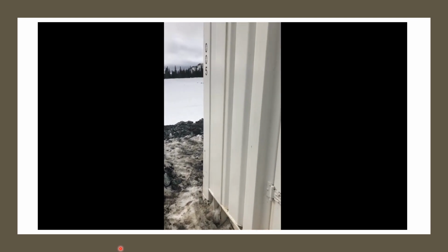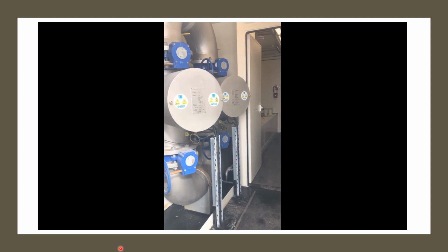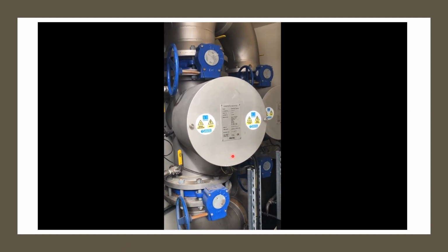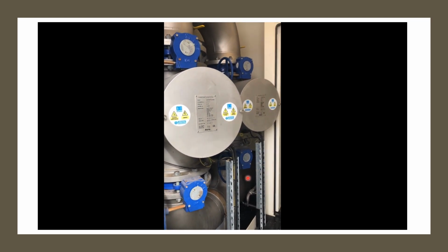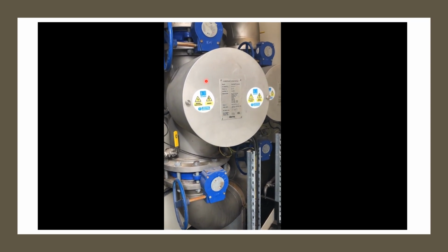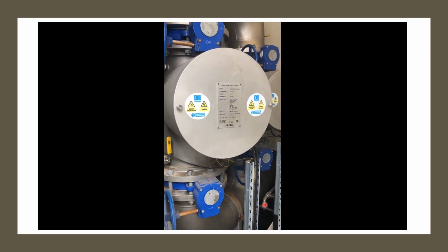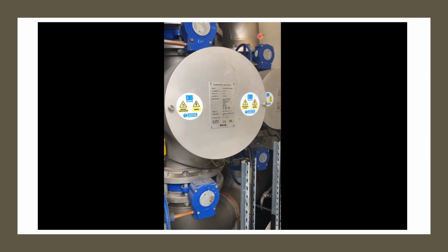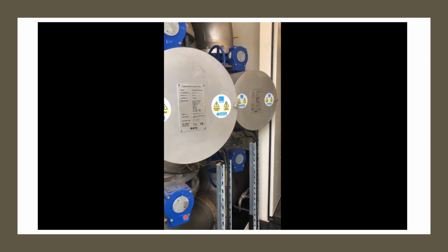And now we're going to swing around the back of one of the containers and enter through the reactor room. You can see the two UV reactors with their corresponding shields installed. Water again flows in through the bottom, floods the reactors and flows around the quartz thimbles, and then exits through the top. You can also see some sample points here on the inlet and another one back here on the outlet. And I'm showing the 4 isolation valves in blue.